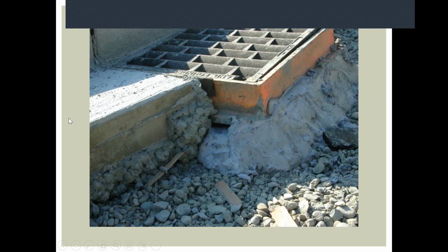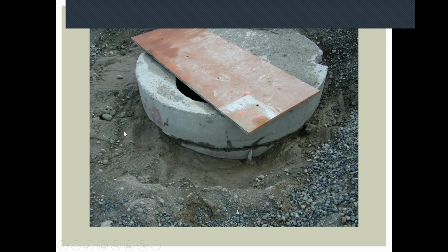Here's a little thing to look for with catch basins. They're ready for asphalt pretty much, but they don't want the grade to have water in it, so they left a little drain hole. So even if this doesn't have a catch basin insert, but even if it did, it doesn't matter. Turbid water is going to be going in. So is it live? Is it grouted? Encourage contractors to grout their manholes, their rings, everything associated with storm as soon as it's installed. Don't wait, because if it is a live system or tying into a live system, it's just sucking muddy water.